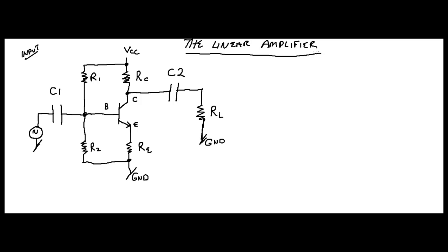Now, as we said, a voltage divider bias transistor, right? That's what we have here. It's biased by this voltage divider. That's your base voltage, which is capacitively coupled to the base through C1. Here's your input, which is capacitively coupled to your base, right? And the load resistor is capacitively coupled through C2, right here, right? We said that when we were drawing it. I just want to emphasize that, right?